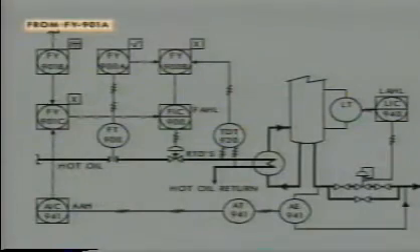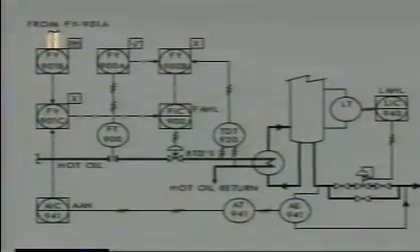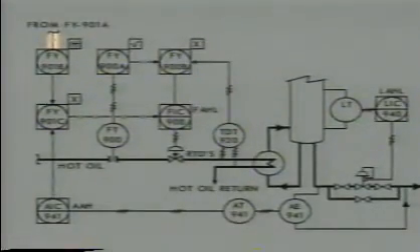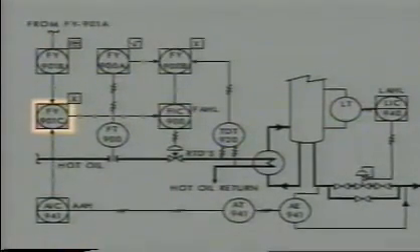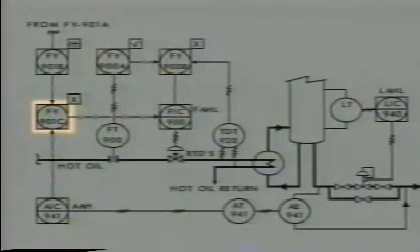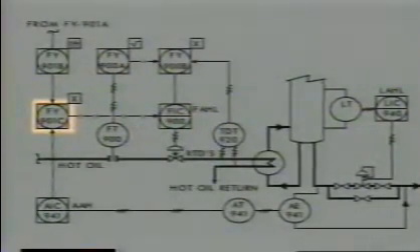This note indicates the source of the flow signal to FY901C. Multiplier function 901C multiplies the inputs from FY901B and AIC 941 and transmits the information via a data link to the flow indicating controller in loop 900.